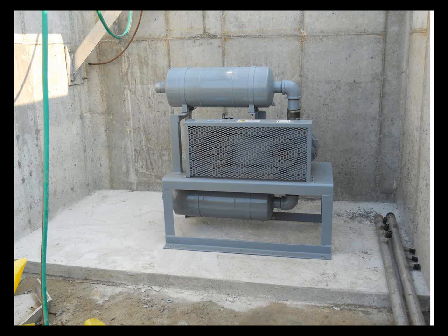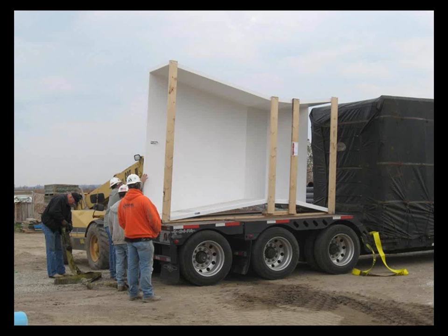This is a blower. Part of our cleaning system on our UV system happens to be air. This blower was installed, and air lines laying to the right side of the slide will be installed and hooked onto the bulbs to use air to help clean the quartz sleeves. This is the Parshall flume as it was being delivered and getting ready to unload and set into the structure. After the flow goes through our bulbs, there's a Parshall flume that keeps track of the flow, which sends that information back to the control panel so that we either light more lamps or dim lamps or turn lamps off depending on what our flow is, or actually open a second channel if the flow gets too high.